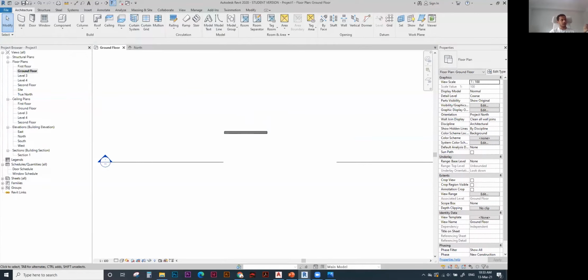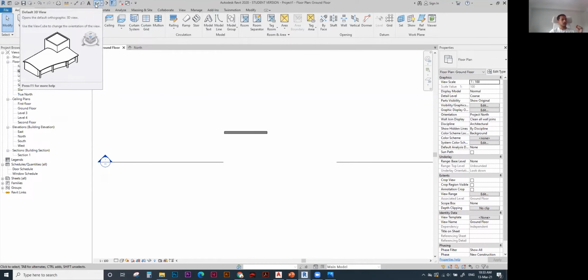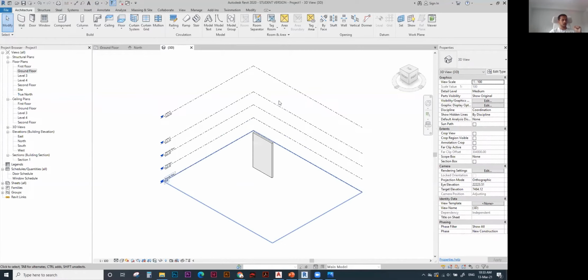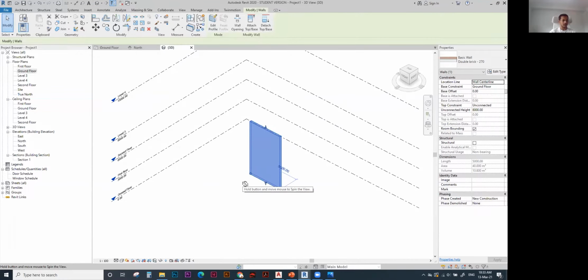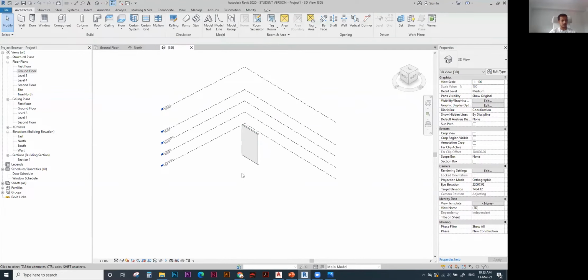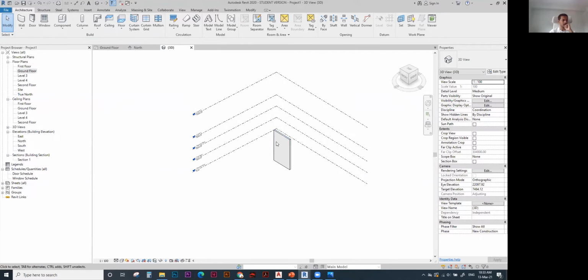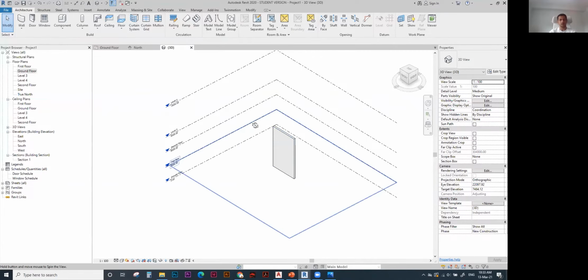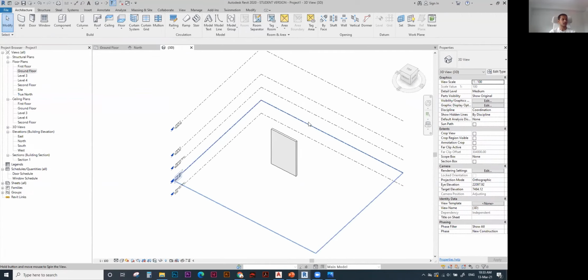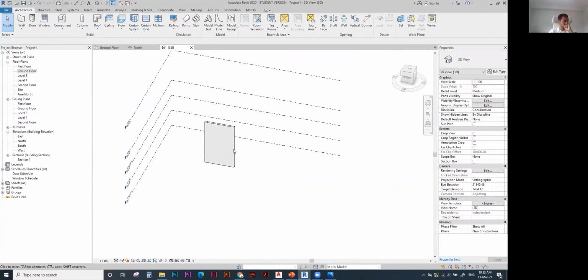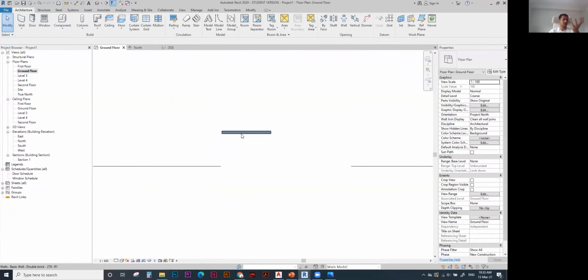But you can also choose to see the wall in 3D. If you go to the quick access bar, like I said, there are other small functions also. One of those is Default 3D View. If I click on that, it's going to show the 3D view of the project. So that's the 5 meter wall that we've drawn. I forgot to mention one thing. Pan in Revit is holding your middle mouse button and dragging, and Orbit is holding Shift and the middle mouse button and dragging your mouse. So that's Orbit and Pan in Revit. I forgot to mention that before.